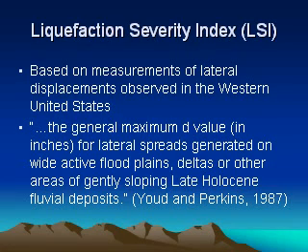With all this spreading that occurs, engineers and seismologists have been trying to figure out: can we determine the amount of spreading? What's the potential of spreading? Well, there isn't anything to exactly pinpoint the spreading, but there has been some investigation and observance of previous earthquakes, especially in the western United States, in which Youd and Perkins measured the magnitude of the earthquake and the displacements. And they came up with what we call the liquefaction severity index.